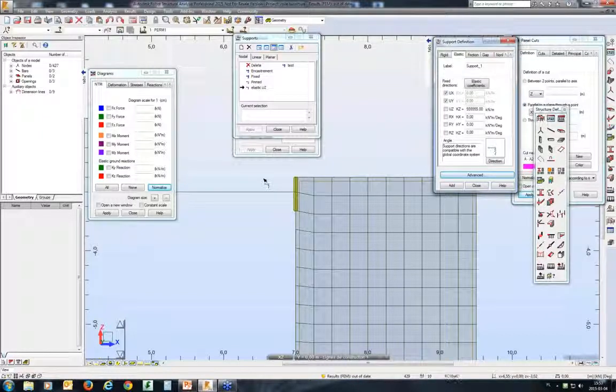Do you recommend remeshing the whole structure after adding panels or meshing only that panel? Rafal responded, it depends on the model complexity. I recommend creating all panels and meshing the whole model without kinematic links, without regular mesh. I have experienced that material is not listed after. And another response from Rafal: meshing does not apply materials to panels. You'll have to run model generation afterwards for calculations.